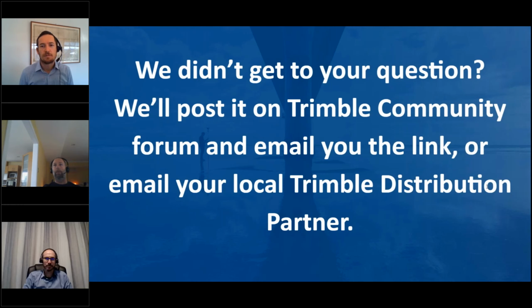I did a lot of testing with the RTX back in the previous versions when we were using GDA 94 in Australia, and I'd love to hear some results and see how good it is, because we used to do that site calibration to translate everything about 85 centimeters to get it back onto the survey marks.